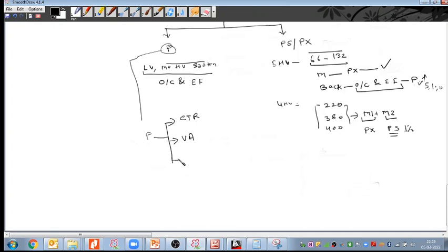Third parameter. In the metering core, we have taken the accuracy class 0.2, 0.2s, 0.5, 0.5s, 1, and so on. But in the P class CT, the accuracy class we need to select as per the IEC 61869. Let us go to the 61869 and see the types of protection accuracy class.